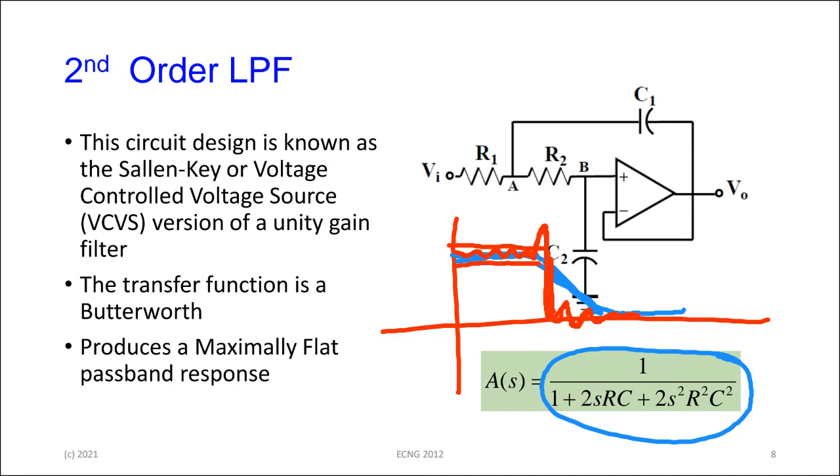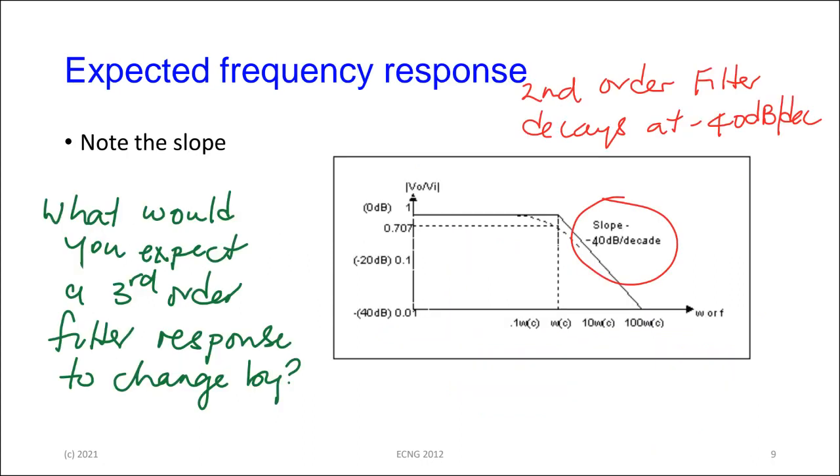Those are probably about as many fingers and toes as most of us have in terms of the types of transfer functions that create the filter responses. There are all sorts of things, and I'll talk briefly at the end of it all about some of the things that you tend to look for. So maximally flat: the response is flat until it reaches omega c.